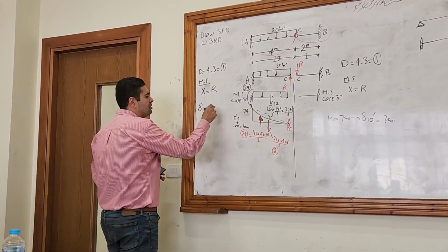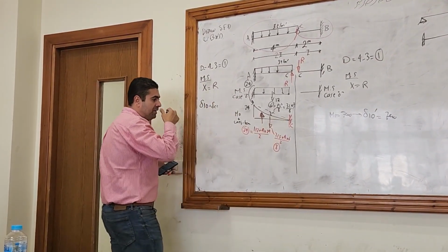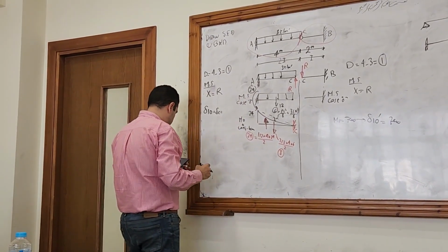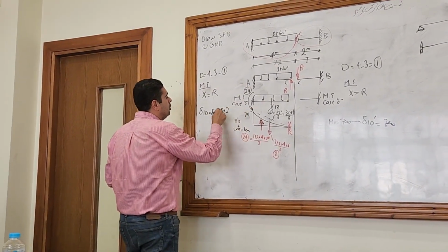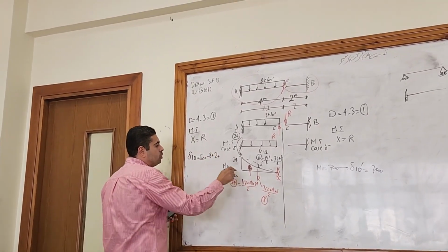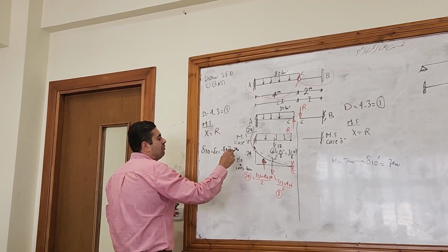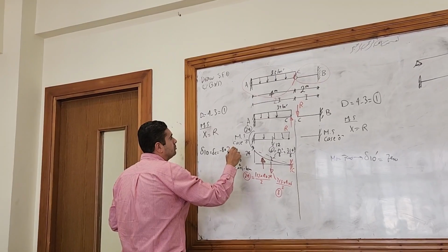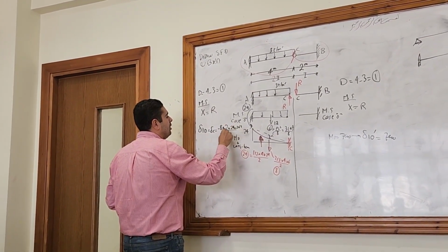Delta 1 node, which is delta at point C, which is the moment here. So it will be 8 in the middle, so times 2, and the sign is negative, plus 24 times the 2/3 of the distance, which is 4, so it will be 2.67, divided by EI.